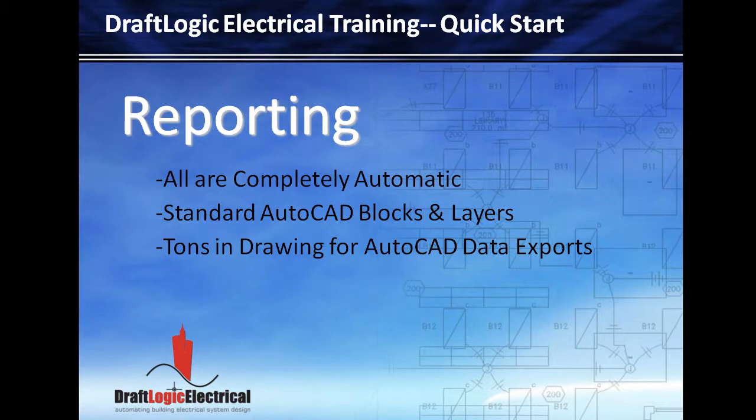DraftLogic Electrical's robust reporting facilities are where you take advantage of all your prior work within the DraftLogic Electrical system. All of the reports are completely automatic. They're generated from scratch using standard AutoCAD blocks and layers. So when they're complete, you can copy, paste, move them from layouts to model space. You can export them to their own DWGs and use them as XREFs. You can resize them, rotate, whatever you desire. There's also an immense amount of information in the drawing usable for AutoCAD data exports if you wish to extract anything out of your DraftLogic Electrical drawing.